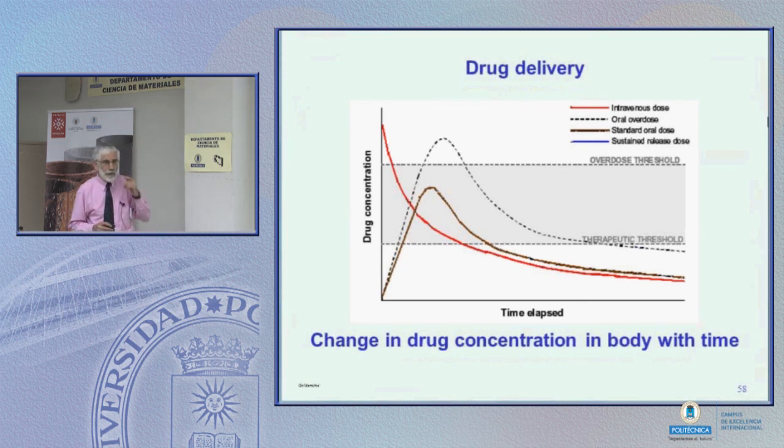Because the diffusion through a metal is x squared proportional to t. It is a parabolic relationship. But through a polymer, you can have a linear diffusion. It is the way that the fluid interacts with the polymer. It is an interface reaction. It occurs where the fluid meets the polymer. And the rate that moves in is linear. It is constant with time.